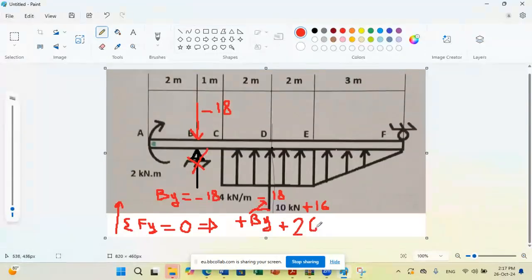For the triangle, a force of 6 kilonewton, so plus 6. And since Fy should be down, because the roller will do a force perpendicular to contact from roller towards the surface, it's minus Fy equals 0.